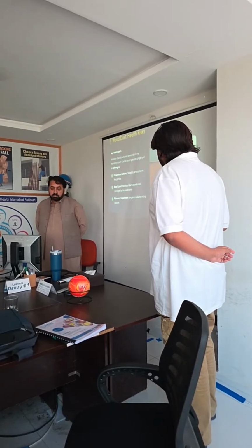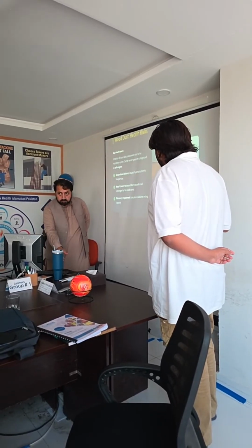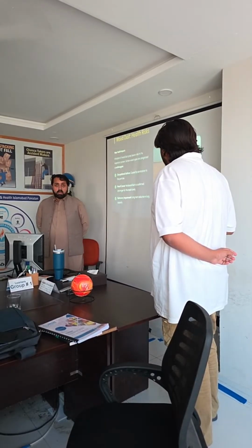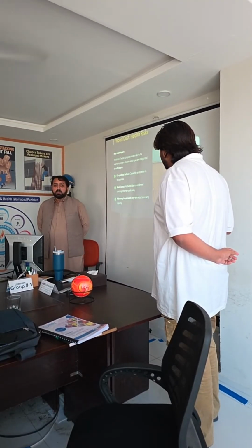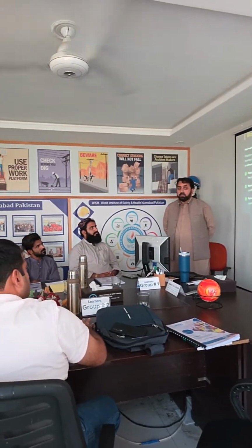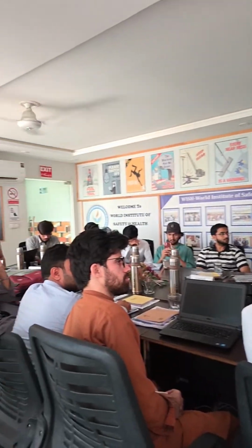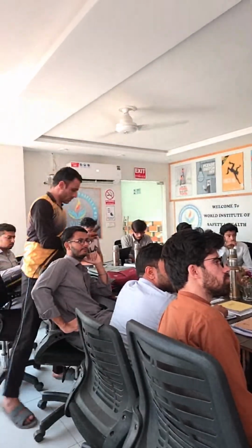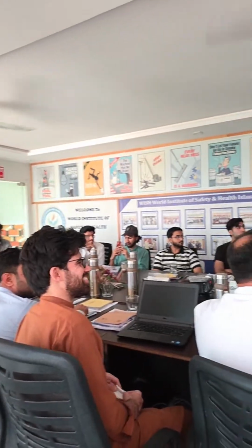Wood dust, health risk, major health impact. Inhalation of wood dust poses a severe risk to the respiratory system. Certain wood types are categorized as asthmagens, causing occupational asthma through sensitization to fine particles. Nasal cancer: hardwood dust is a carcinogen, which may cause cancer of the nasal cavity. Pulmonary impairment: long-term reduction in lung capacity.